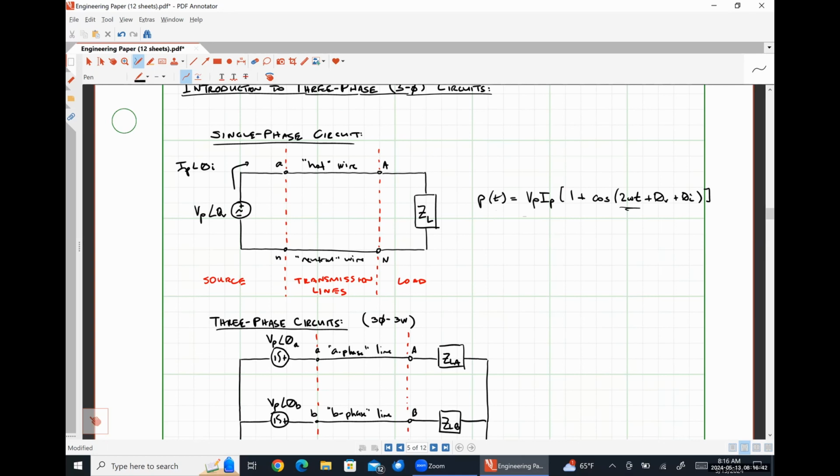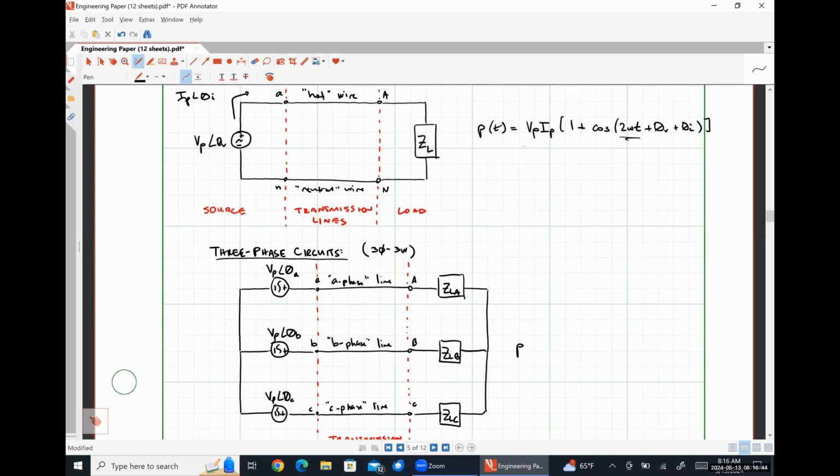which means the torque developed by that motor is also going to be changing in time, okay? Now, the instantaneous power developed by a three-phase system, and it'll be a couple of days until we derive this, is literally just going to be 3/2 VP IP cosine theta V minus theta I. And actually, there's a mistake up here, but it's fine. This should also be cosine theta V minus theta I. That's what I get for freestyling part of my lecture.